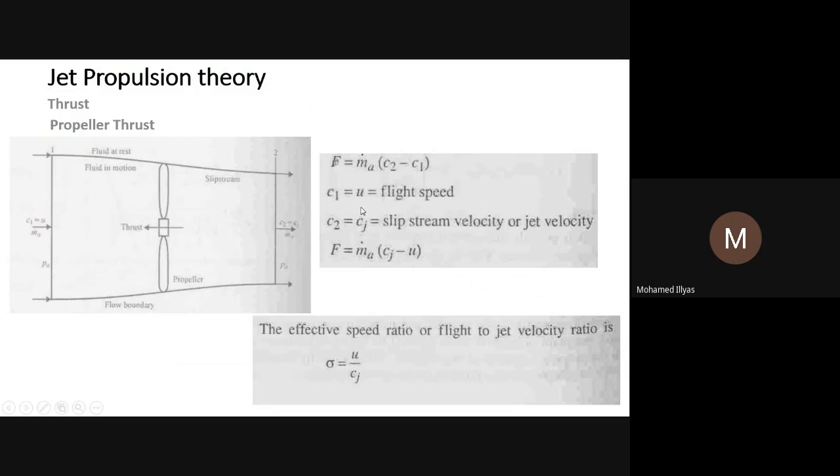So that is a huge change in velocity. Further, when the fluid moves here, it is slipping over the blades. That's why that flow stream is called a slip stream. And there will be a further rise in velocity when it makes a nozzle-like passage, because the flow will take that way.